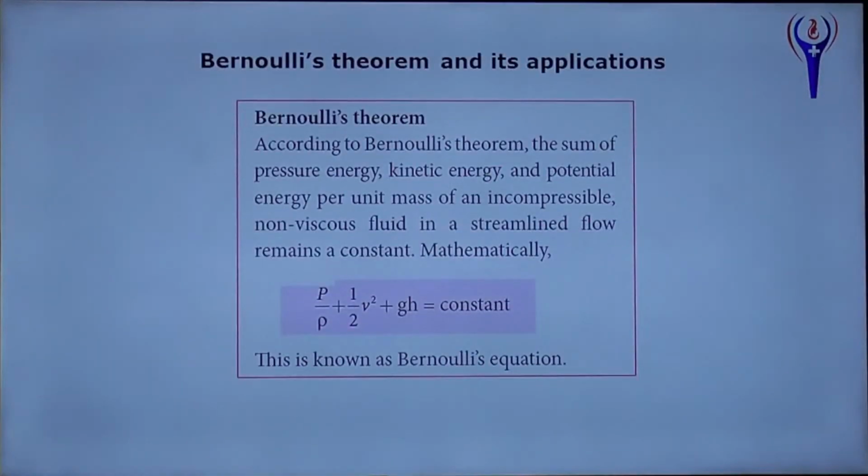And Bernoulli's theorem, that also we have discussed. According to Bernoulli's theorem, the sum of the pressure energy, kinetic energy and potential energy per unit mass is constant. This is for an incompressible non-viscous fluid in a streamline flow. P by rho plus V square by 2 plus g h equal to constant.